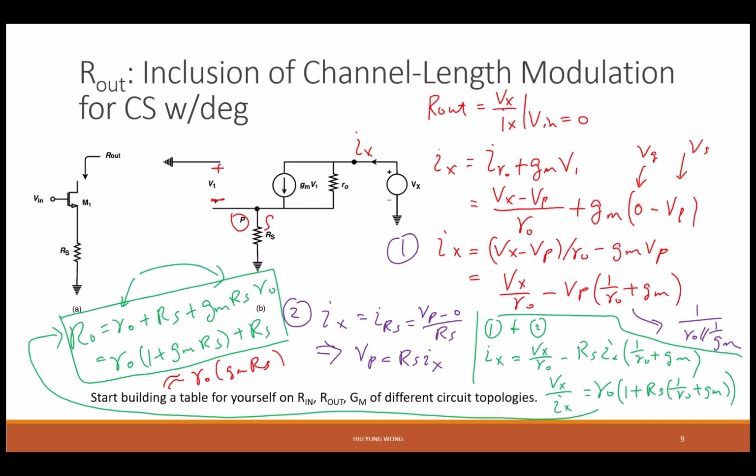Yes. Now, so he said that, isn't it that we keep saying that we want an ideal voltage amplifier to have a low output impedance. That is true when you're driving the next stage. However, in that case, you have very low gain. Okay, so now we want to make it high, so we have high gain. But to solve your problem, later you will see that we need to cascade it with another stage, which is source follower, which does not change its gain, but it reduces the output impedance.